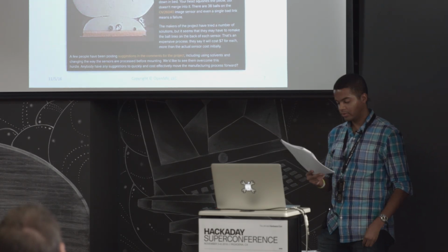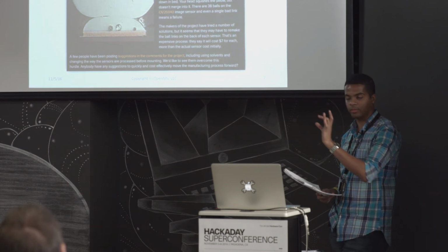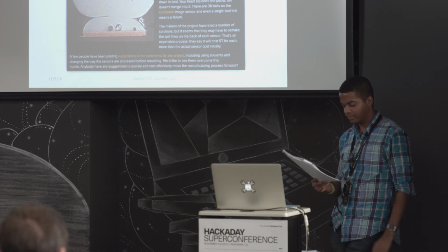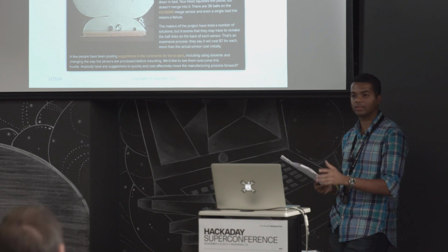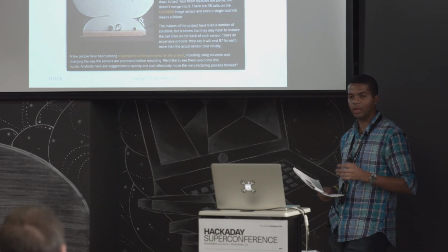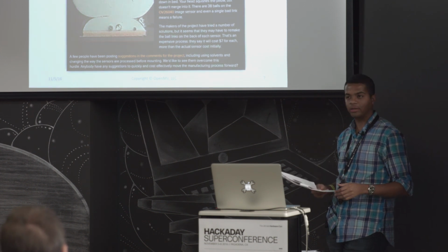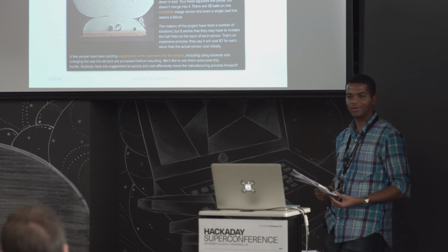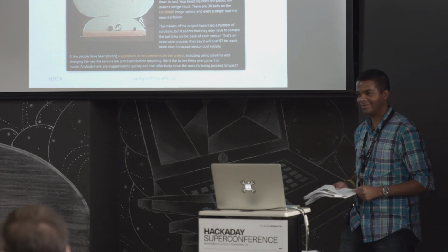And how did it happen? Well, it turns out that the camera chips have little tiny solder balls in the bottom of them, which go bad over time. Unless they're completely sealed from the outside world in a temperature- and humidity-protected environment, the solder balls corrode, they rust, and after 10 years, they're completely worthless. There's no way you can actually put the camera down on the PCB anymore. We actually made Hackaday's Fail of the Week because of this. Someone gave an anonymous tip, and bam, our failure was on the front page of Hackaday.